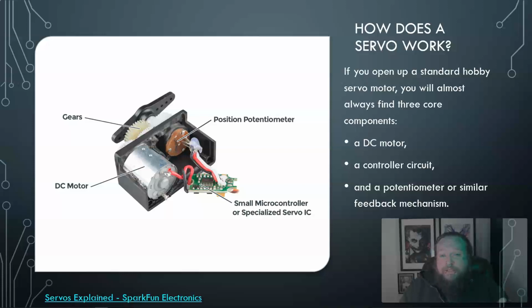And we'll be doing this through a library, and our code will make it easier, but you have to realize that it is a separate controller that, once it receives its signal, is working asynchronously at the same time as your controller. So it's not that I tell the servo to move and my code will sit there until it's moved and then be done. You've kind of got to wait a bit before you move on to anything else if you're expecting the servo to be at a specific position before any other work continues. So you need to take that into account.